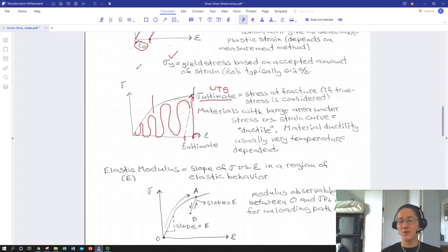Energy per unit volume has the same units as stress, which are the same units as the area under the stress strain curve. And that's a good way to remind yourself that the area under this curve is literally the energy required to either strain something and keep it in that stretched, compressed, or twisted configuration elastically, or the energy necessary to make it yield and plastically deform it.